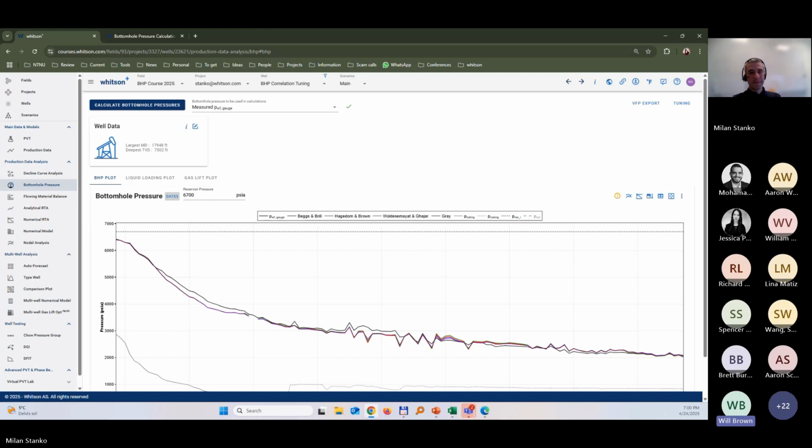That's fine, I don't have any more to cover. I was just curious, for continuous injection down a backside or cap string, or even just soap sticks, how you adjust for the fact that you're having a foamed fluid column and how far that column's making it. If there's any significant work done on that, it's just kind of a blank area for me.